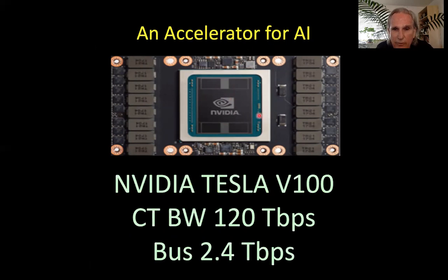A problem that you run into is that the bus is at 2.4 terabits per second inside this NVIDIA GPU. And you could put a chip over here and have 4 of these things coming off. The problem is that's as much as you can do. At that point, you can't go any farther. That's the biggest AI machine pretty much that you can make. You can reprogram it to get some more AI power out of it, but you've pretty much exhausted copper interconnections. Because if you go any farther, it slows it down too much.